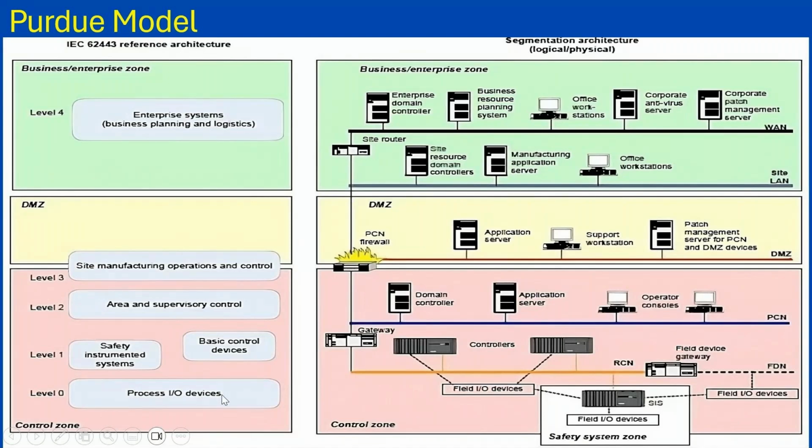All those come under it, but level 0 particularly contains the components of the industrial control system, which are the sensors, transmitters, valves, etc. When it comes to level 1, you have seen the distributed control system in the previous slide, similar to the safety instrumented system, which is another high-end PLC. So these input outputs, whatever is getting received from here, the CPUs, so the complete brain resides in level 1 actually. And this is one of the keys to monitor, control, and safeguard the process.